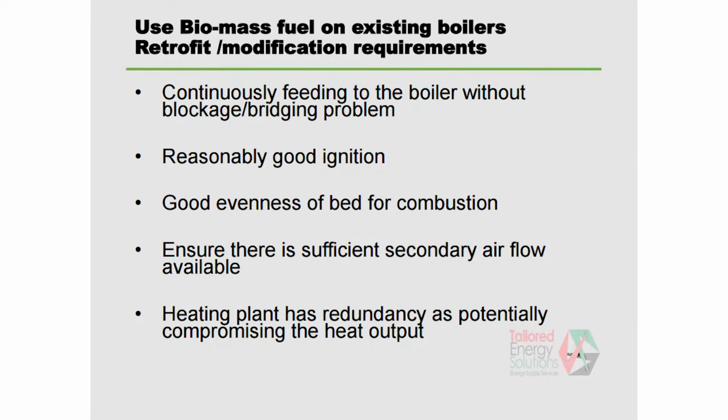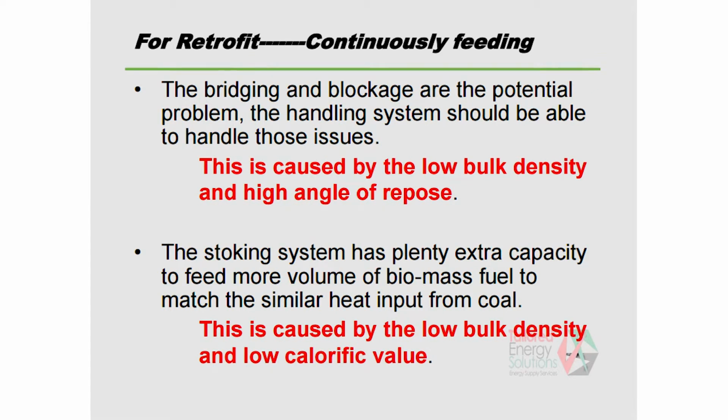Okay, heating plant, you have redundancy. Why I say that? Because the heat transfer is determined by the flame temperature, and the temperature from wood waste is going to be lower, so that your capacity can be compromised. Yep, for retrofit,